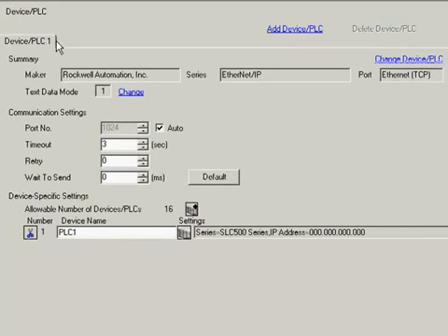Note that for 6-inch and 3.8-inch panels, 2 separate drivers are supported. Any of the larger Proface panels can support up to 4 different device and PLC drivers. Each driver can then support multiple PLCs, which you will see in the allowable number of PLC devices. So our driver on Ethernet can support up to 16 individual CPUs connected.